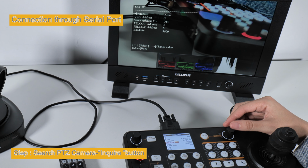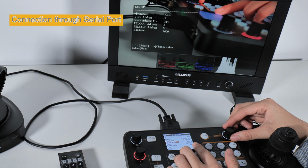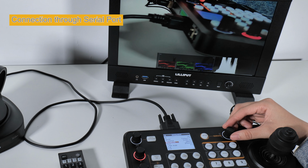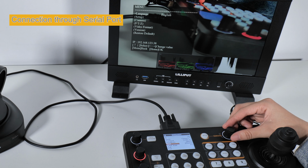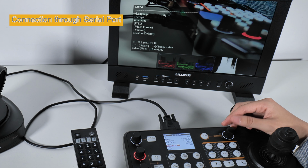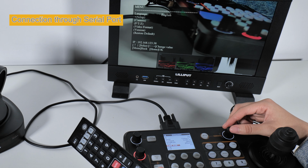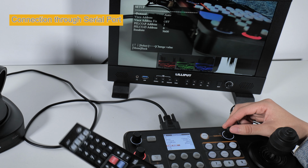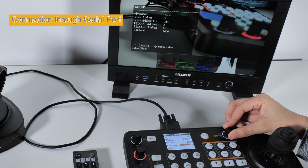And we can see from the screen, the baud rate is 9600. And the port we are using is RS232. And then the camera address of the PTZ camera is 5, so we should set it to 5.